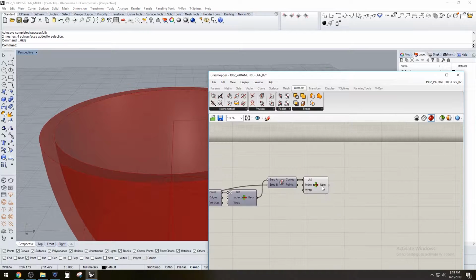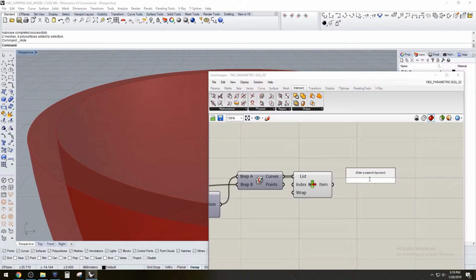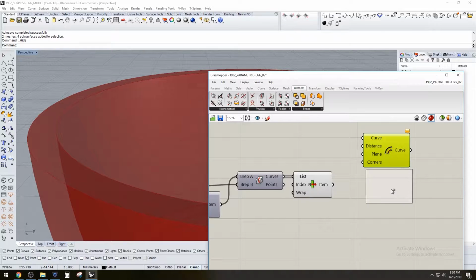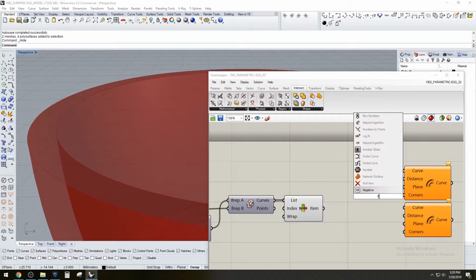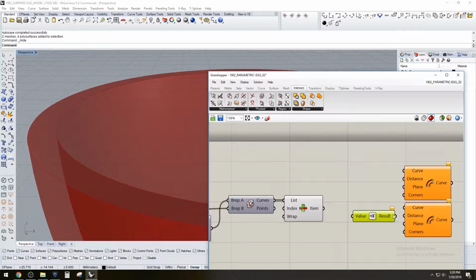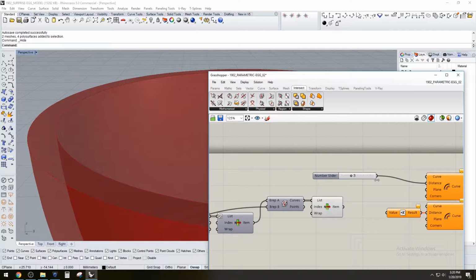And so to give it some thickness, we want to offset it. So we offset it out, and we're going to offset it in. Since we're going to offset one out and one in, we know that one's going to go negative and one's going to go positive. So let's do a 3mm offset, and we'll do one there, and we'll plug this one here.